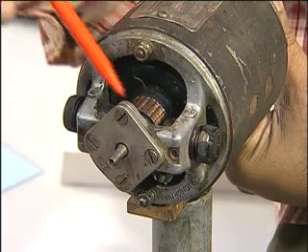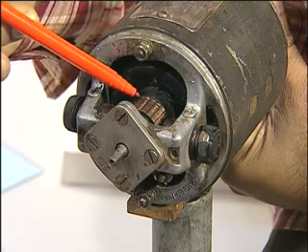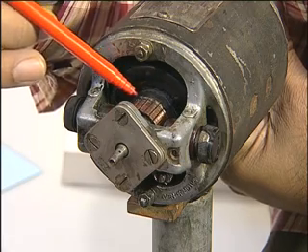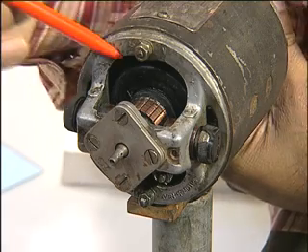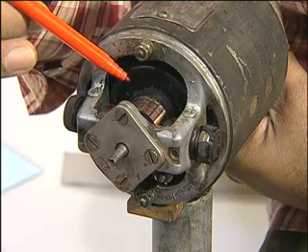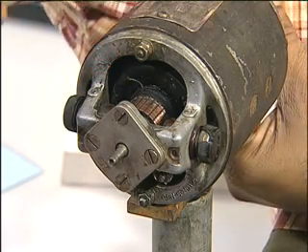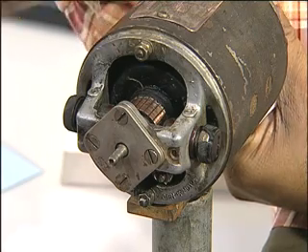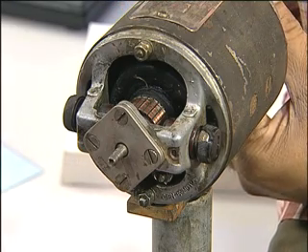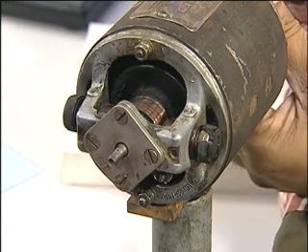There are two brushes here on these two sides, and the commutator segments make contact with the copper coils by virtue of being soldered. Now, at this end there are very fine solder joints which make connection with the coils inside on the rotor, and this is a 38 slot motor, and therefore, you have much less ripple as compared to a 2 slot or a 4 slot motor that we just saw. 4 slot meaning you have 4 slots on the rotor with 4 coils. 12 slots means 12 coils. 38 slots means you have 38 coils in this here.